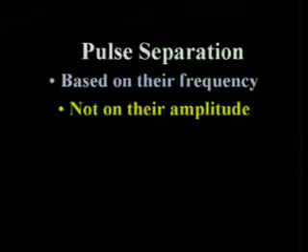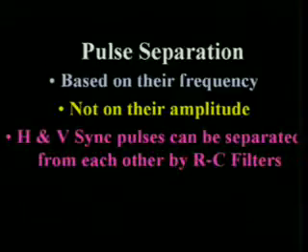Therefore, to separate these pulses, we have to depend on their frequency and not on their amplitude. To separate horizontal and vertical sync pulses from each other, we need the RC filter. Let us see here in this diagram.